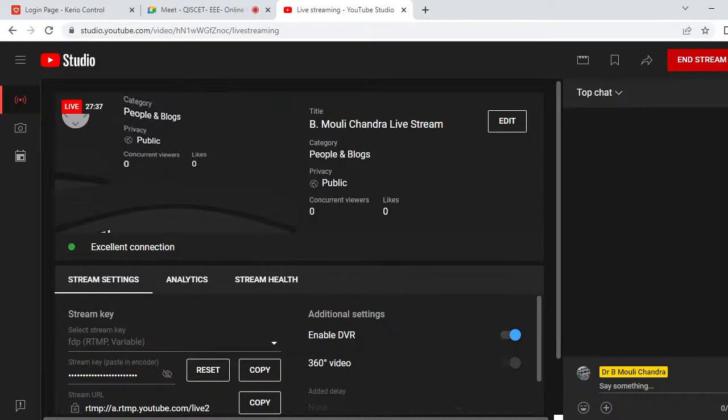Now the comparative voltage profile for the Brazil 136 bus RDS, case 3 and case 4. In this case, we observe in figures 7A and B that the CPSO algorithm gets the better voltage profile as compared to the PSO and MPSO, for case 3 and case 4. In figures 8A and B, which show the comparative VSI profile of the Brazil 136 RDS, you observe that the CPSO algorithm gets the better voltage profile as compared to the PSO and MPSO algorithm.